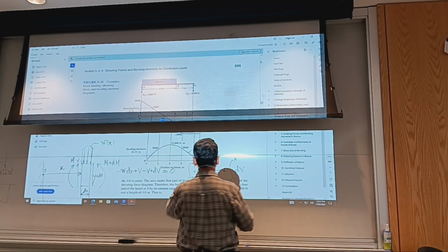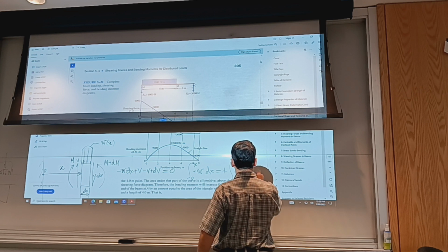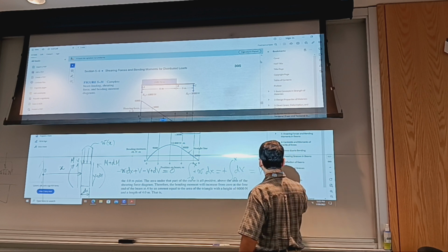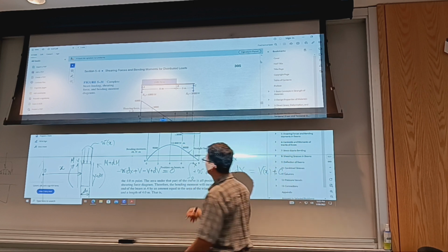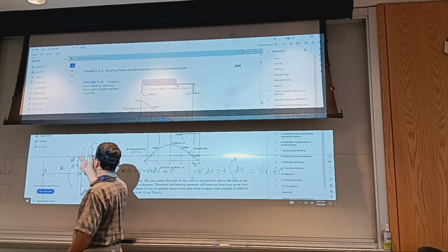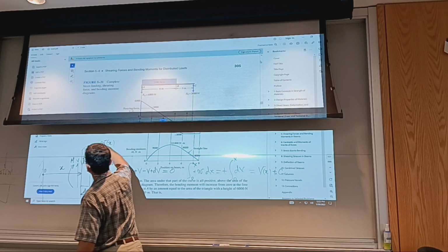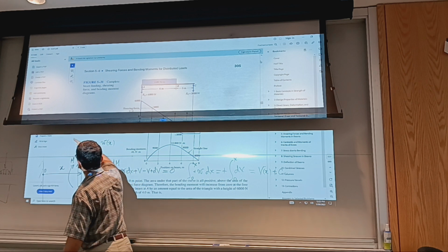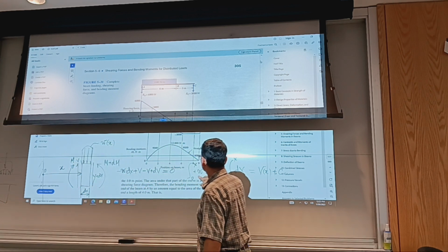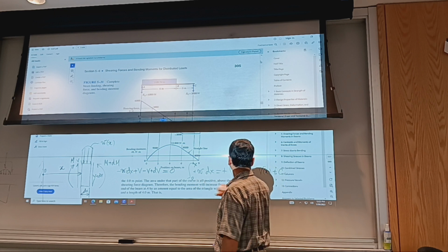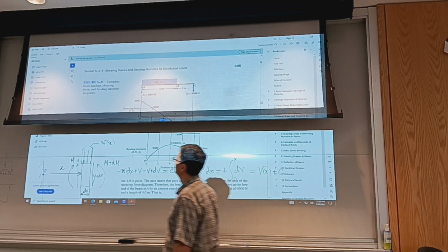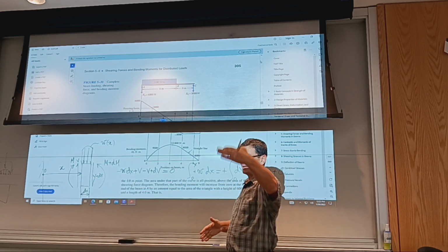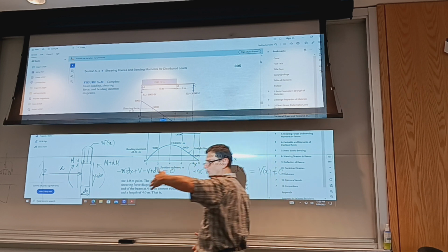Anyway, so we have this one, and this part of the integral is going to just be V at x plus a constant of integration. And here I'm integrating over the shear diagram. And if it's constant or linear, then this takes a specific form, and you can solve essentially for V as a function of w. If it's missing, then this constant of integration is just going to be the sum of the concentrated forces to the right.